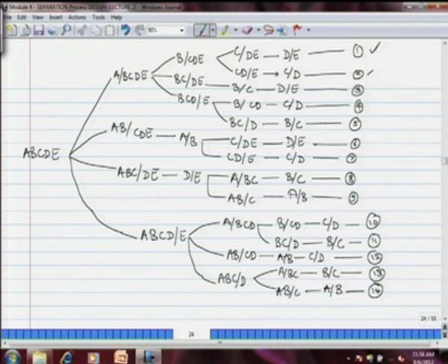Then the second sequence is ABCDE mixture, A taken off first from BCDE, then BCDE mixture split into half, BC together being recovered at the top, DE together recovered at the bottom, and then these binary mixtures are further split as BC and DE. Then in the third possible sequence, we have separation of A again from BCDE mixture first, and then BCDE quaternary mixture is split as BCD together and E being separated, that is indirect sequence, and then we are left with a BCD ternary mixture which is again split in direct and indirect sequence, like B being separated from C and D and C and D being split in the 4th column, or BC being separated from D and the binary mixture BC is split in another column. So, in this way, if you start writing, you can write 14 different sequences as shown in this figure.